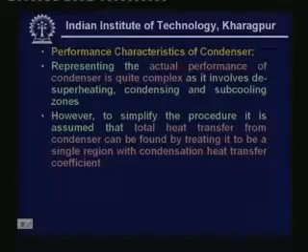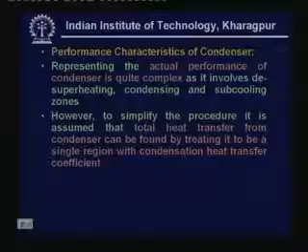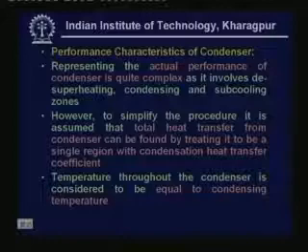So as I said, however, to simplify the procedure, it is assumed that total heat transfer from the condenser can be found by treating it to be a single region with the condensation heat transfer coefficient. In fact, the justification for this was given while discussing the condensers. And temperature throughout the condenser is considered to be equal to the condensing temperature.